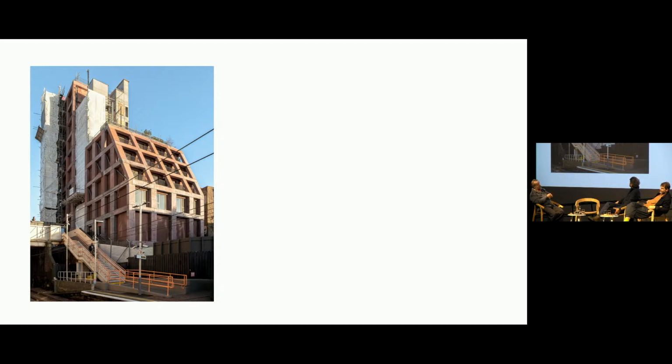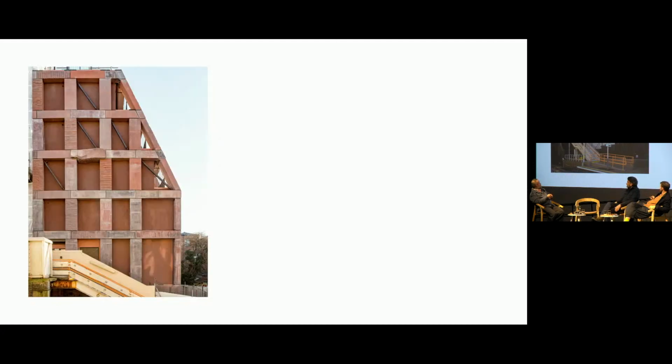The lift shaft needed 1 hour and 20 minutes of fire resistance, and was going to be a steel frame clad in 4 layers of plasterboard on the inside and the outside, very, very expensive. So as a cost-saving solution, we built a stone lift shaft from single-story slabs of lava granite, 100 millimeters thick. They prefabricated each level in a goods yard outside of London. They delivered them, and they built a 13-story lift shaft in 1.5 days in stone. So that was quite an orthodox achievement.